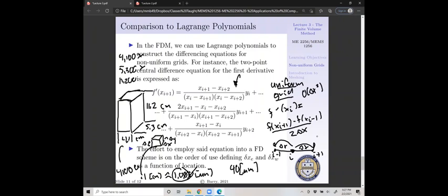Now, if this were millimeters, for instance, I'm going to cut out 3 orders of magnitude here. That's still 243 million elements. So if you're trying to always construct a uniform grid where you're solving for that one mesh size that allows you to have a perfect dx, dy, and dz, where it's uniform in all dimensions, that's a lot of elements. That's a lot of memory. And that's a tremendously long solve time. So sometimes you just can't get away with it.